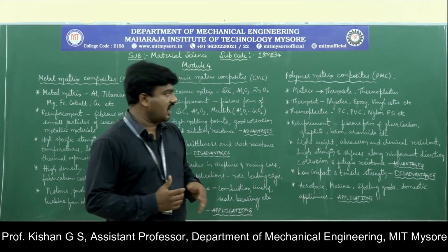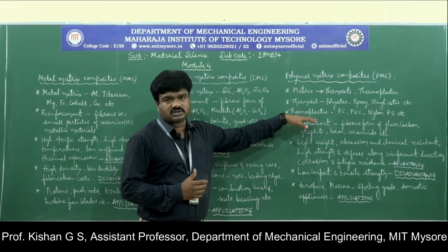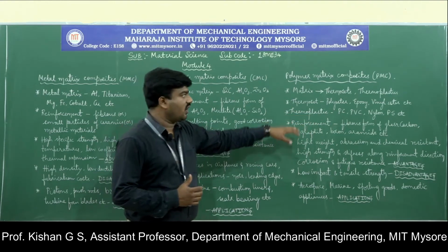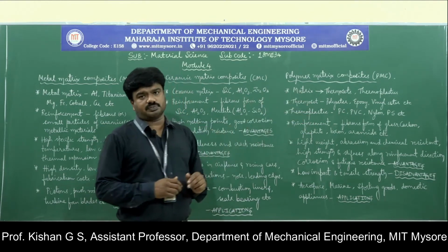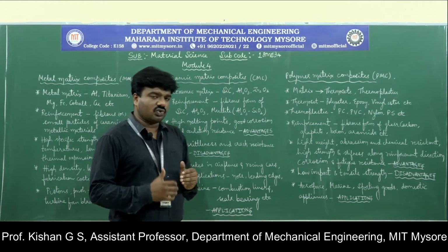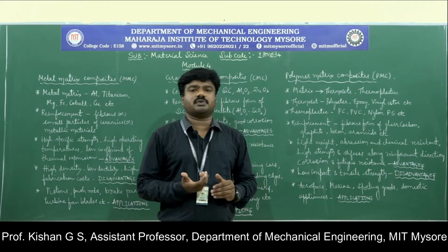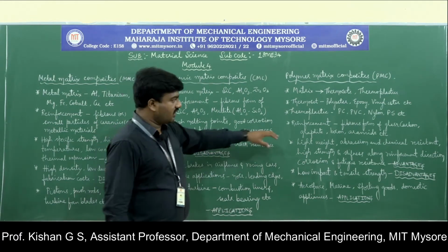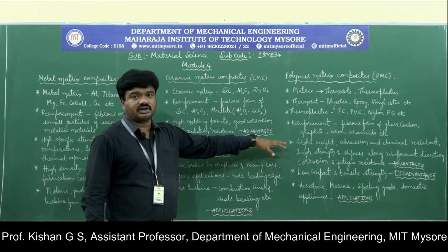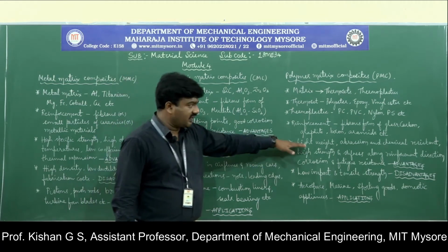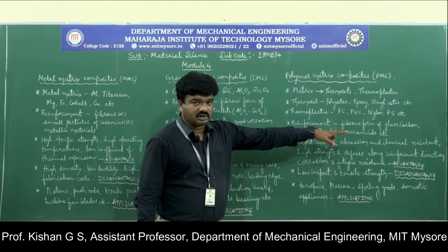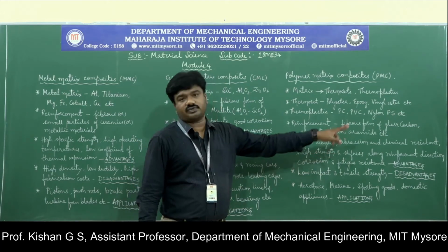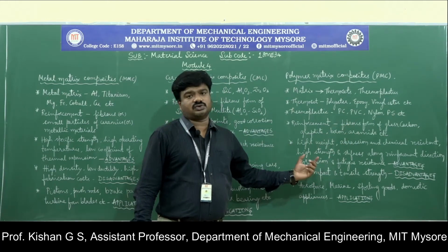Okay, so those are the fibrous materials which are considered or preferred reinforcements when we opt for polymer matrix composition, and it has its own advantages over other types of composite materials as well as the conventional materials. So the list of advantages includes lightweight, abrasion and chemical resistance, and high strength and stiffness along the reinforcement direction. This is the point of focus now.